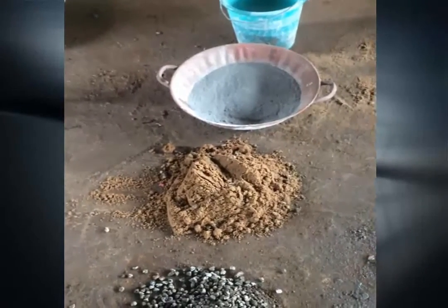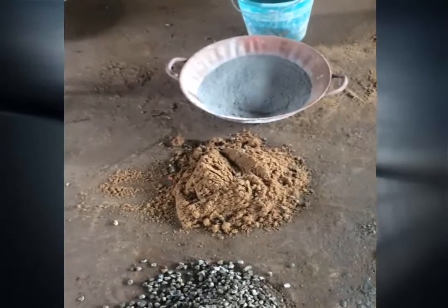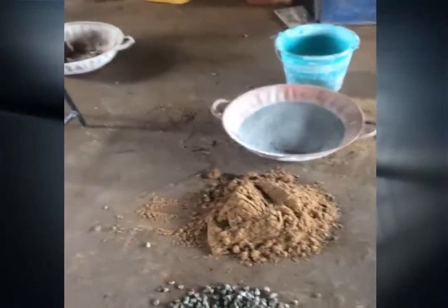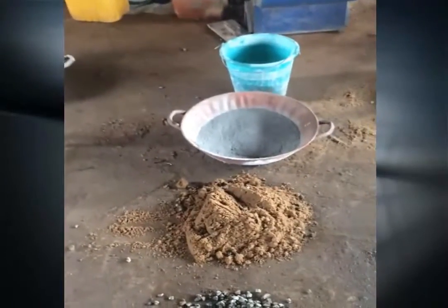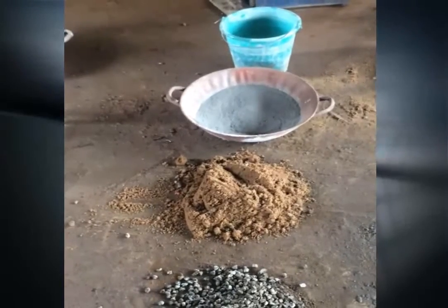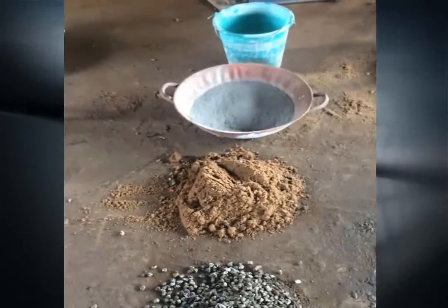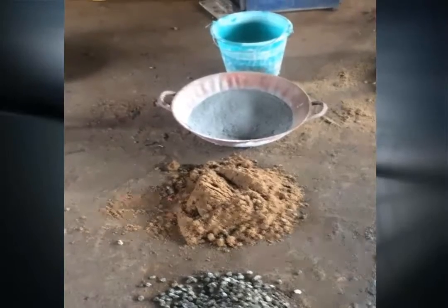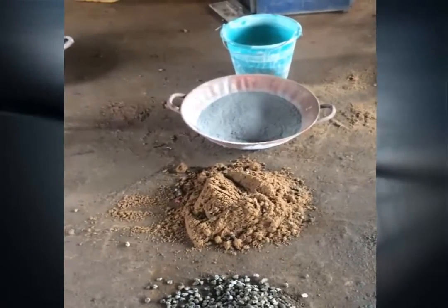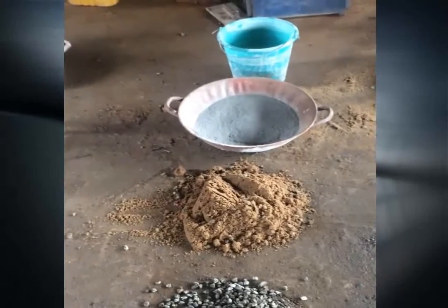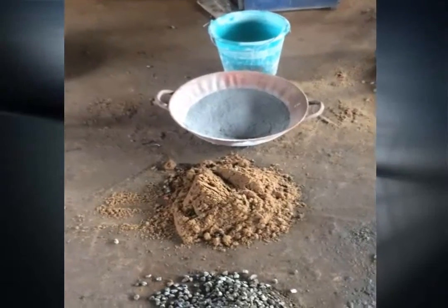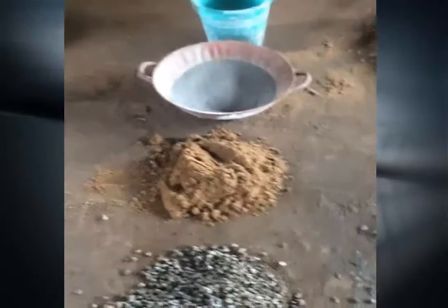One of the methods of checking if it is fit for purpose is to carry out a concrete cube test, which will measure the compressive strength of the concrete and relates directly to the required design strength specified by the designer. A cube test is usually a minimum requirement from the client to provide evidence of cube test results to ensure compliance with the designer's requirements.